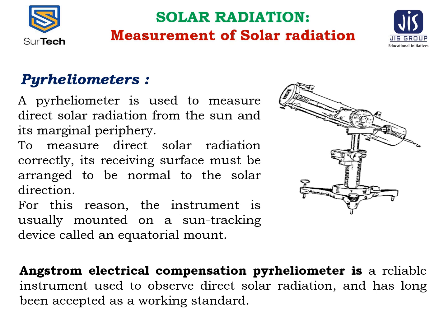This instrument has a rectangular aperture, two manganese strip sensors 20 mm by 2 mm by 0.02 mm, and several diaphragms to let only the direct sunlight reach the sensor. The sensor surface is painted optical black and has uniform absorption characteristics for shortwave radiation.